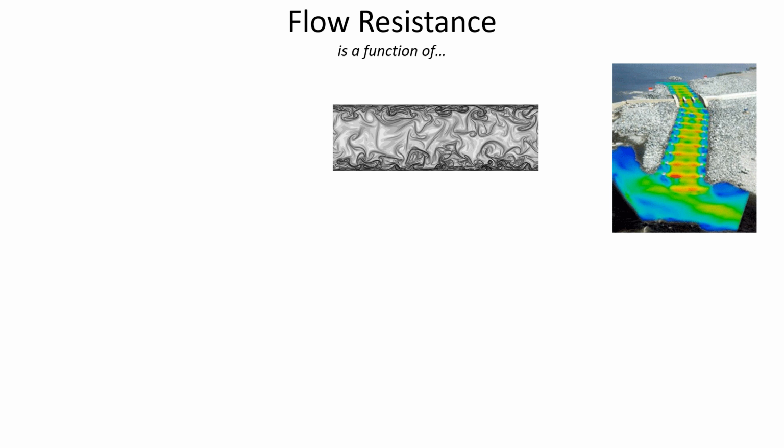Friction. Okay, friction, what do you mean? Friction from the sides of the channel. Okay, good, that's right. So it's this effect of when it's near the edge of the channel, it's experiencing some resistance to flow. We talked about the no-slip condition in fluid mechanics and how water that is in contact with a stationary surface will have the same velocity as that surface right at the edge, where the two are coming together at the boundary layer. But then the further away you get from that boundary, water is able to slip over itself, and so the highest velocities will be at the center.